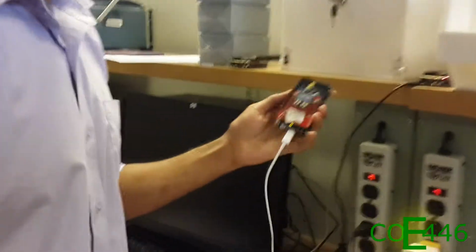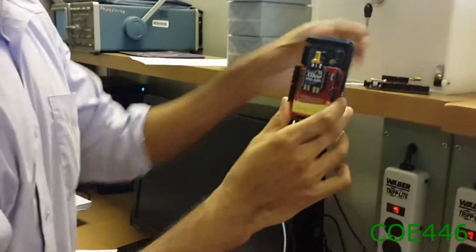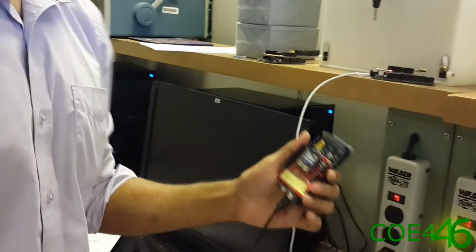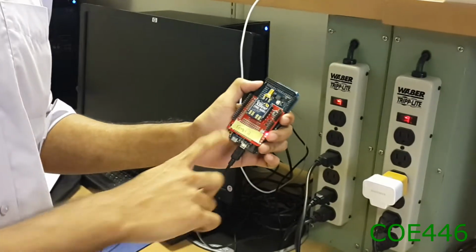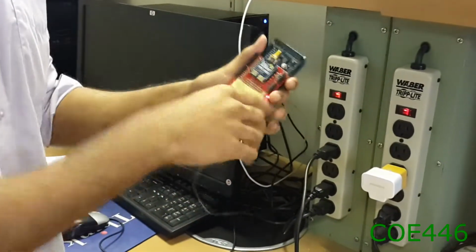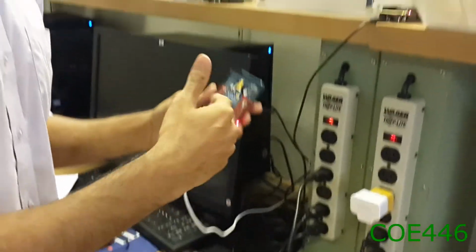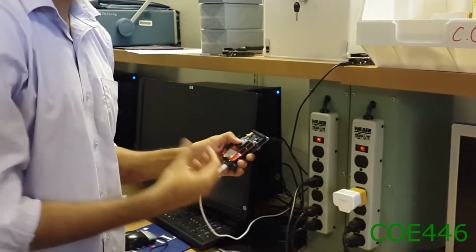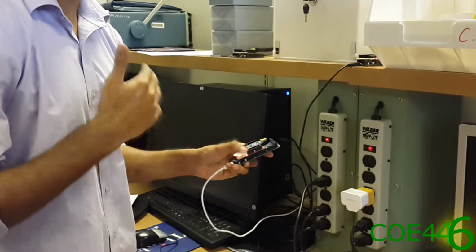Here we have one reference node, and the ID of this reference node is reference node number 2, and the target which is near this reference node number 2 is target number 2. So what's going on here? Target 2 is broadcasting its ID, and whenever this reference node receives a broadcast message from a target node, it extracts its ID, creates a new packet, and sends it to the coordinator along with its reference node ID.